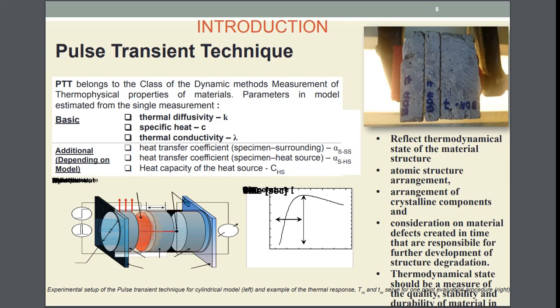For example, if you put your samples inside the chamber at 45 degrees Celsius like in India, and then at midnight you will feel maybe 23, so it will be like a 20-degree delta T. This is quite too much. So it's recommended to do experiments at night because of the low change in temperature, to get relevant values. In this graph, we are missing the axis titles, but I can explain it.